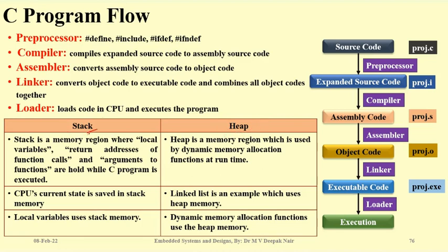We already talked about stacks, right? The stack is a memory allotted in the main memory, where, whenever we use any branch instruction like function calls or interrupts and so on, some of the data which is very useful for the present program is loaded into the stack memory, right? And we know that the stack in ARM Cortex-M4 has a specified size of memory.